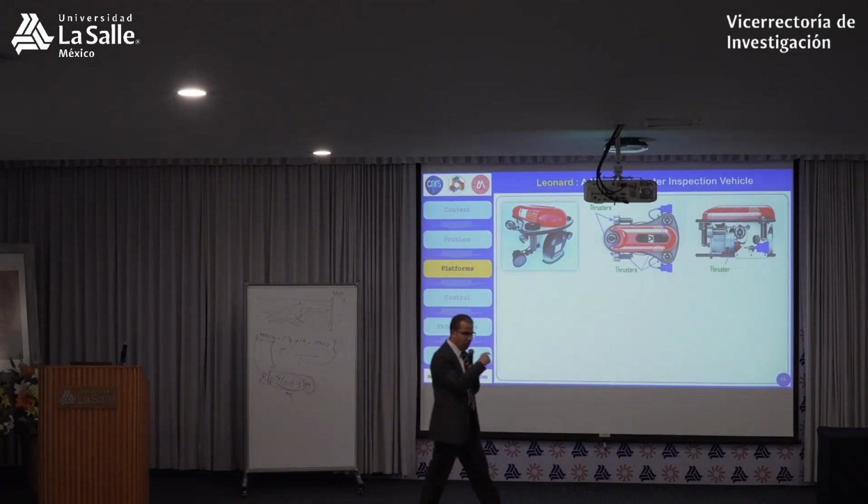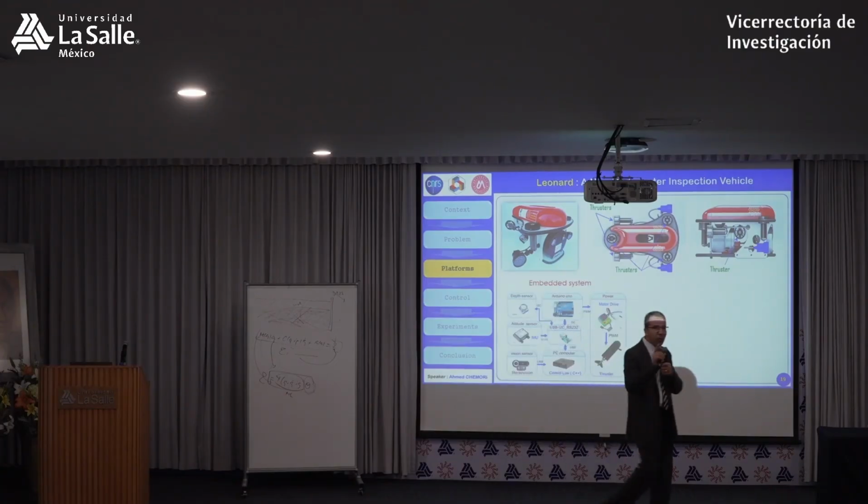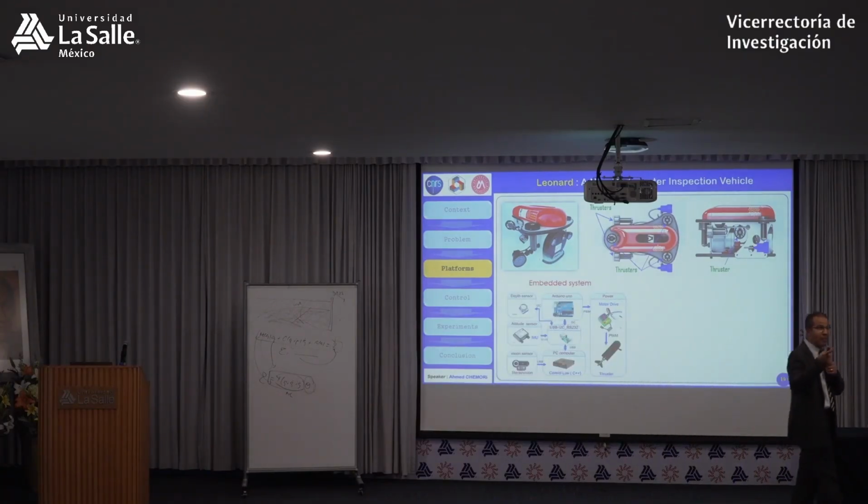However, pay attention, the big problem in this case is not the actuation, it's the measurement. Because among the 6 degrees of freedom, we can measure only 4. We can measure the depth, because we have a depth sensor. However, we cannot measure X and Y. We can measure also roll, pitch, and yaw, because we have an IMU inside.